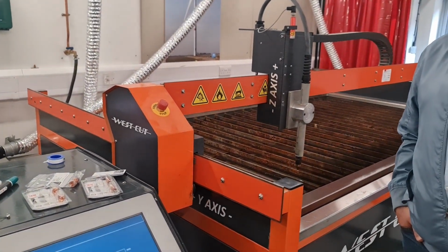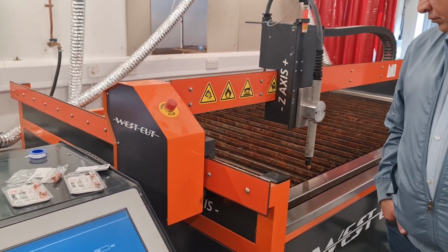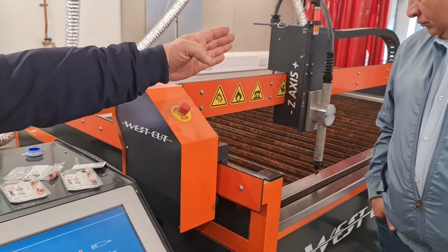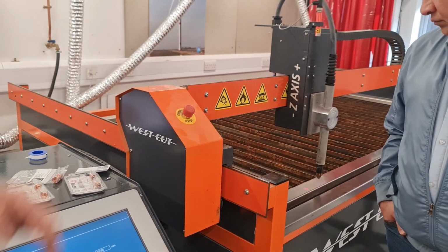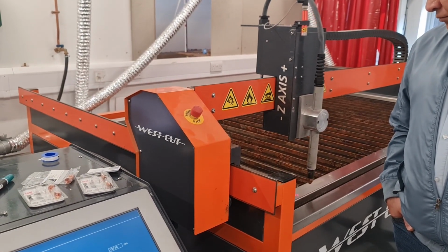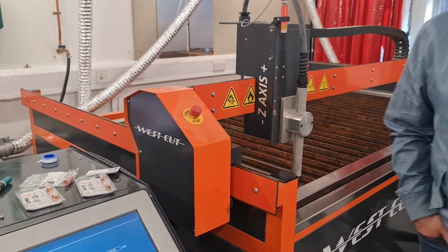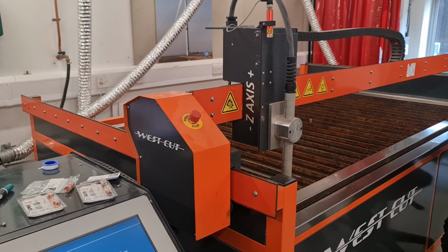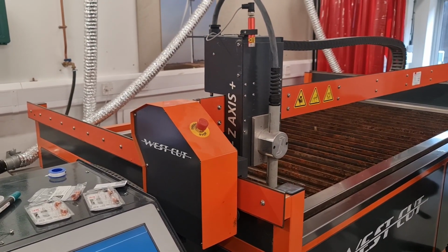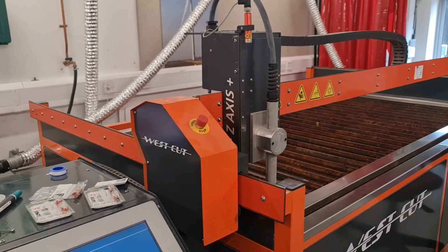So it's homing now. Is it homing? Yeah. Now it's making the hole. So first it will make Y1, then it will correct the squareness of the bridge, Y2, and it will make the Z. Obviously these have to be green to start working with the machine. So now it's done.